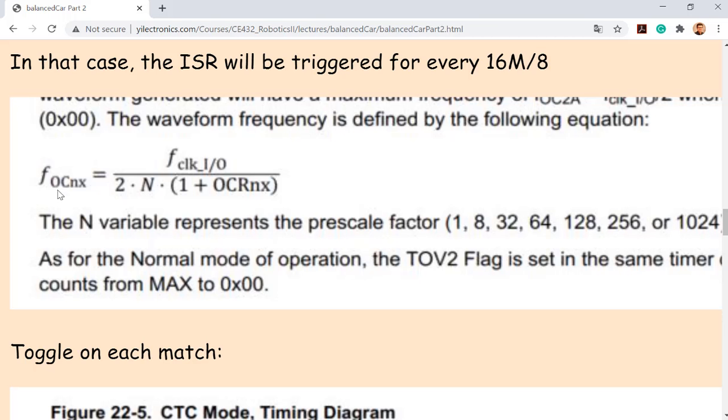You don't have to update the PID error really quickly, as long as your wheels are moving, so the car will not tip over, because you always have something moving. If the wheels are not moving, then it's going to fall over. So it holds the previous PID value before you get a new one, and keeps doing that.